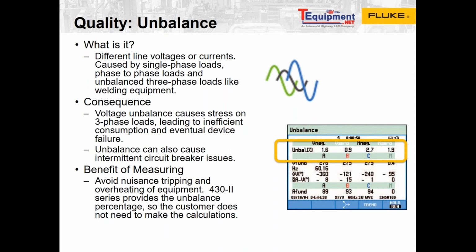As we covered in the voltage unbalance section, voltage unbalance will cause current unbalance. And then properly diagnosing voltage or current imbalance has several immediate benefits, because a voltage imbalance can cause a current imbalance, and diagnosing a voltage imbalance can help avoid motors that trip current overload fault protection devices. So you can avoid elevated motor temperatures and long-term wear by diagnosing voltage unbalance specifically.